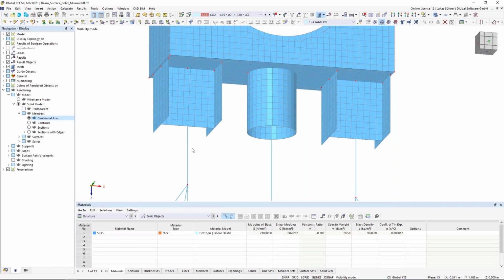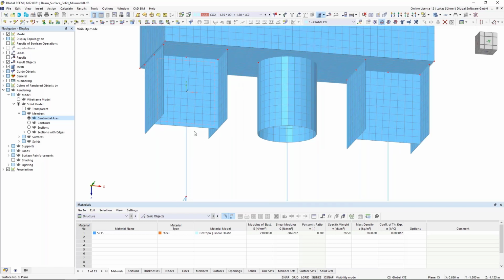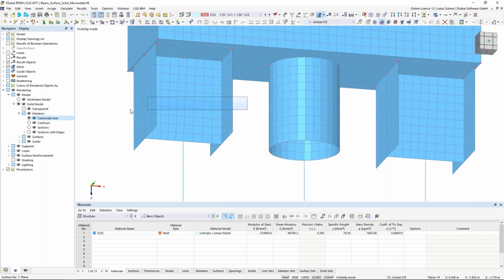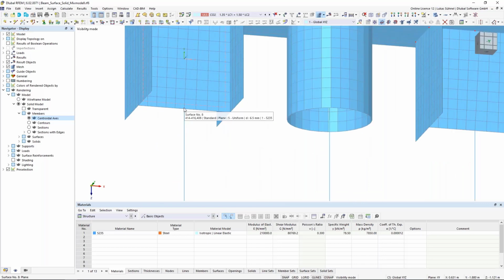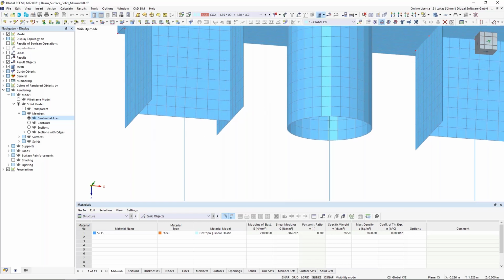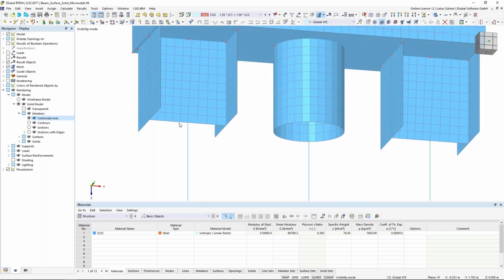often you don't have a proper or a correctly defined connection. You can see it on the left. The surfaces in that area are now basically supported on only one FE node, the FE node where this member connects to the web of this beam. That is of course not correct. You would definitely get singularities in that area, and the stiffness transfer is also not correct.